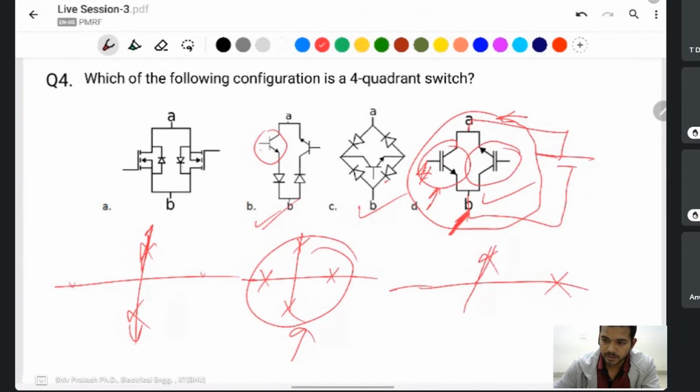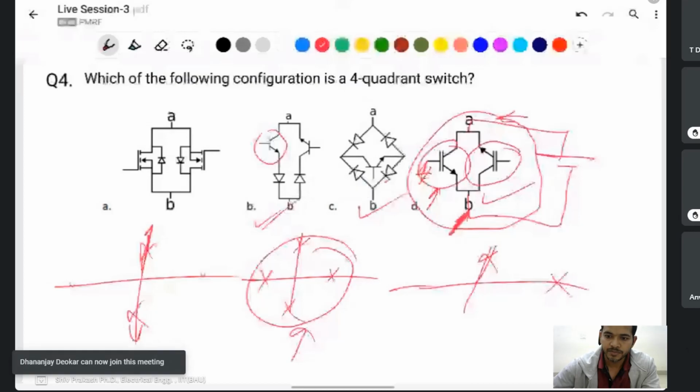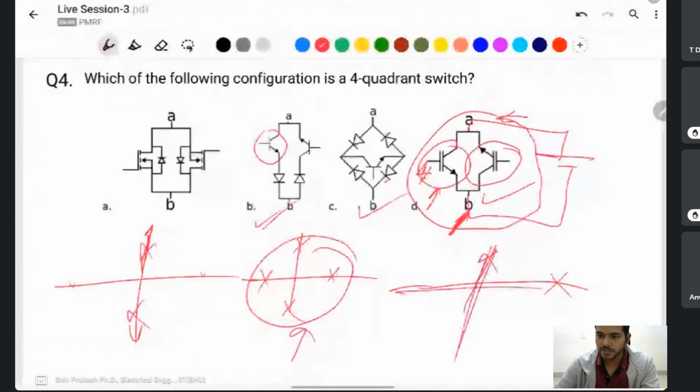So that's okay, but for the transistor on the right, the source terminal is positive and the drain terminal is negative. In that case, how will it block? If you are not providing a gate signal to the transistor on the right, will it block that voltage, sir? Yes, it will block voltage. If you are not giving gate voltage, then both polarities of voltage will be blocked across the drain-source. This one is an IGBT.